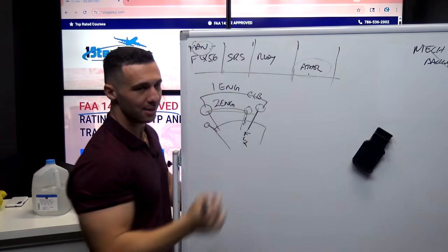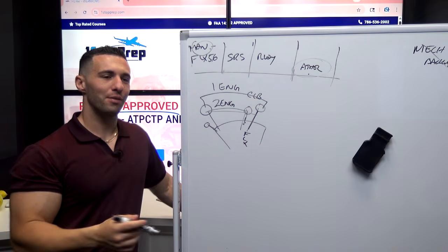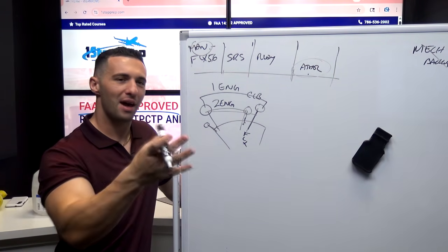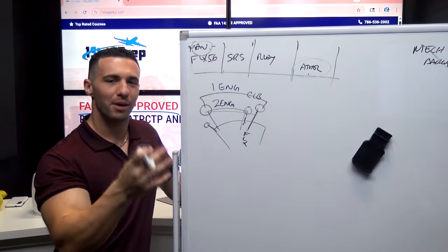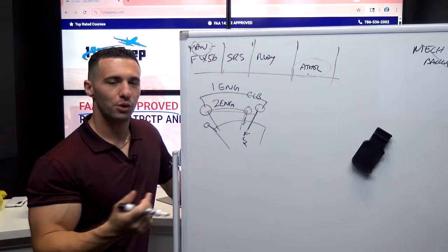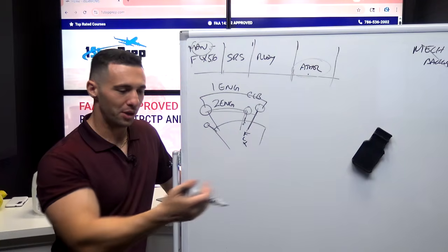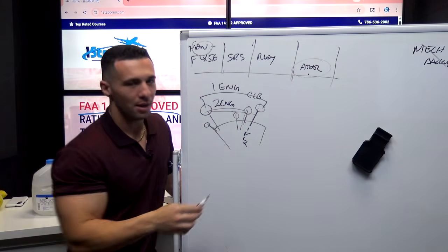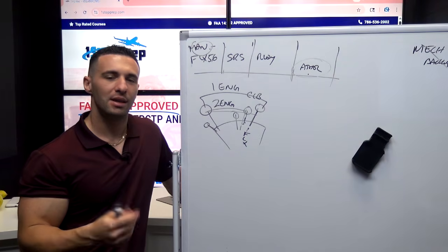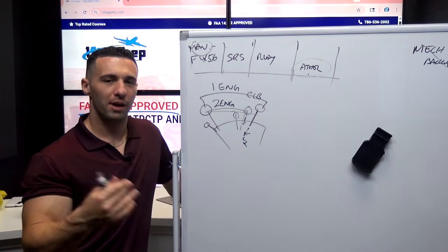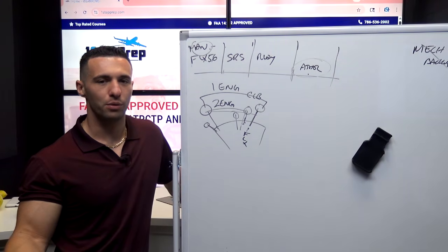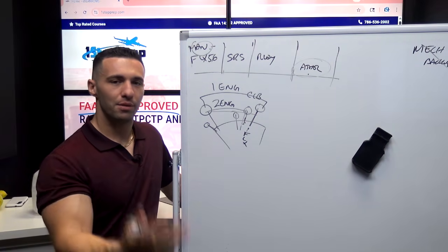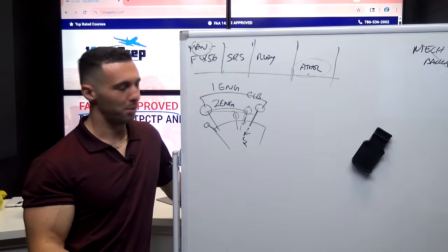In fact, if you don't move the thrust lever to flex MCT, the FMA gets upset and just starts flashing at you, LVR CLB, right? And you can do this demo even with 2 engines. If you reduce the thrust back a little bit to, say, here, just below the climb, it'll spit out this ECAM, right? And the ECAM will say AUTO FLT A/THR LIMITED, thrust levers move. It's basically saying you're limiting my ability to give you a full range of auto thrust capability.